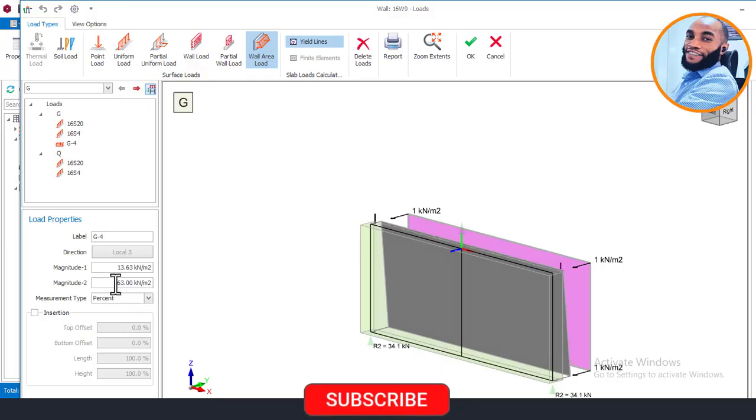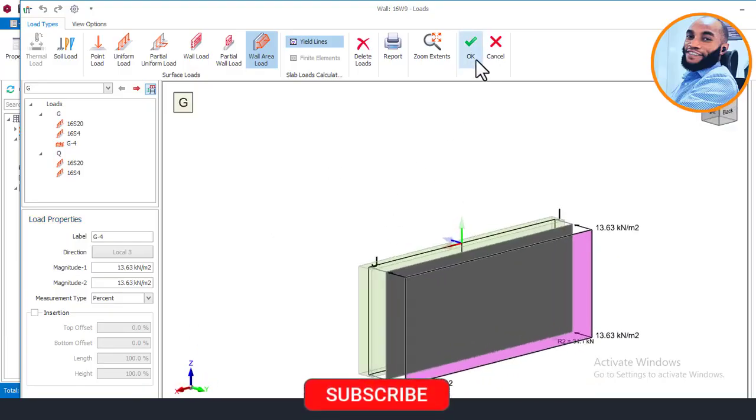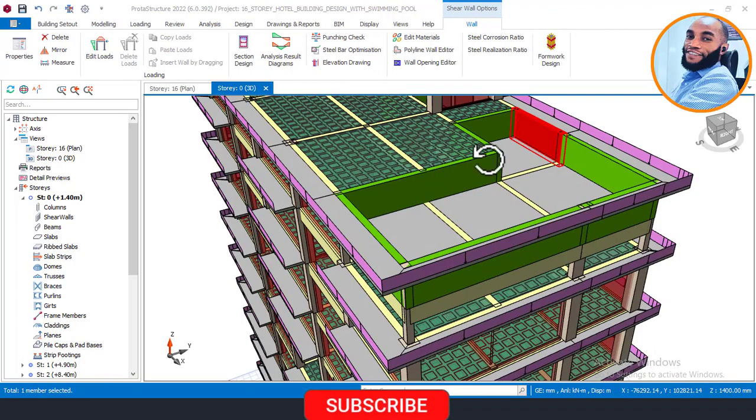Sorry, let me just undo everything here. 13.63, that's fine. And I'll click on update here. Okay, and I'll go again right now and then say okay here. And we are almost done, remaining just 2 walls that we are left to define our load.